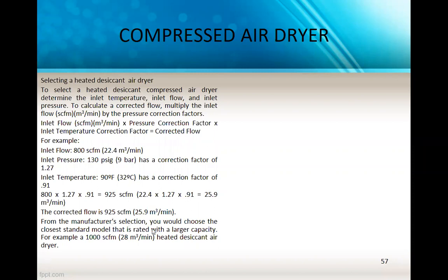From the manufacturer selection, you would choose the standard model that is rated with larger capacity. For example, a 1000 ACFM desiccant air dryer.